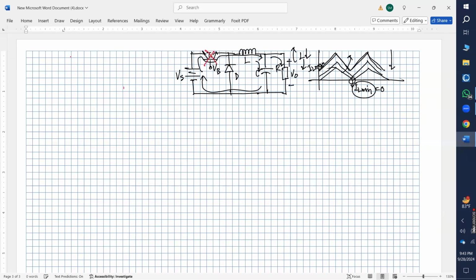All the inductor current, because the inductor doesn't like the current direction to change, will go through this resistance, and it cannot move through this direction because this is open circuited. So it will go through the diode in this direction as much time as it gets, because how much time it will flow depends on the value of L, C, and R, right?